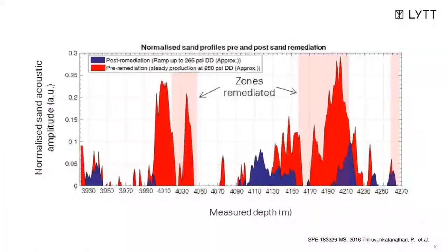Let me first start by introducing the concept of a sand log. Prad has mentioned a couple of times the idea of sand log, and you've seen from the video, basically we receive acoustic signals from the fiber deployed downhole. From this acoustic signal, we extract the characteristic attributes of sand entering the borehole.